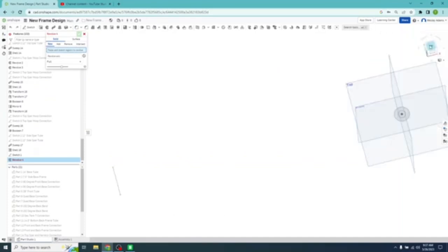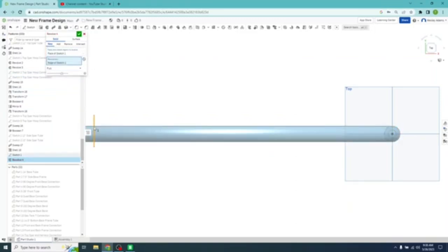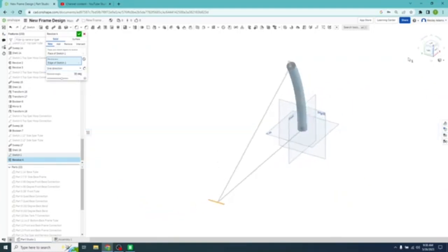So I'm going to go to top plane real quick. And these are going to be the surfaces, so both this one and that one. Make sure you select both. That way to hollow out the center. Solid new. Revolve axis. Click on that, it'll turn blue. Once you select it, left click on our axis of rotation. Good. But instead of full, we want one direction. Here, I'm going to change our angle so we can kind of look at that.